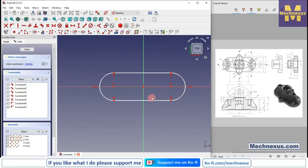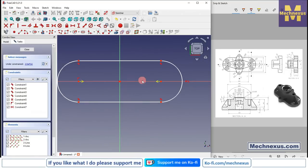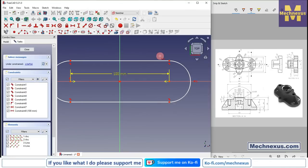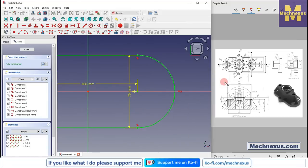We will delete it, and now we will use the symmetricity. Select this point and axis, and we will delete it, and this center to center distance is of 100 mm. So we will select the horizontal dimension and provide the value of 100 mm, and now we will select a vertical dimension and provide this 76,